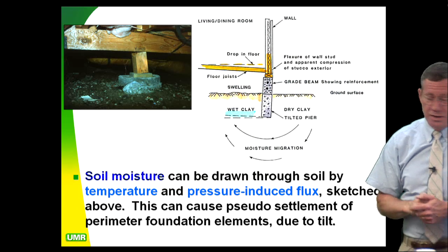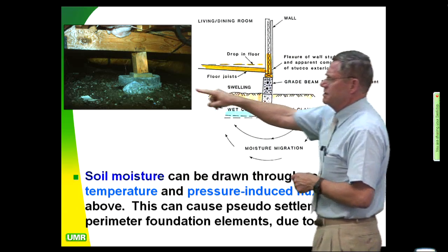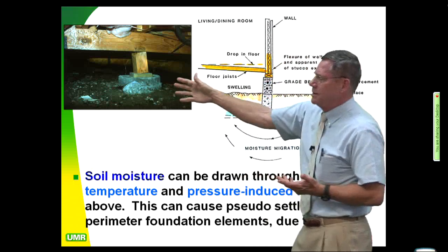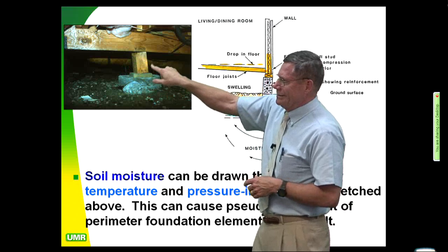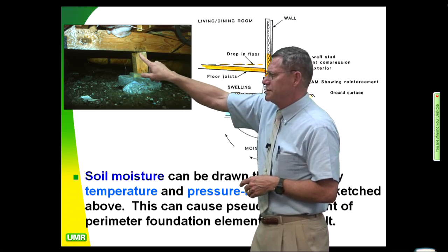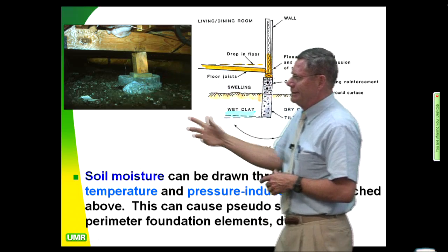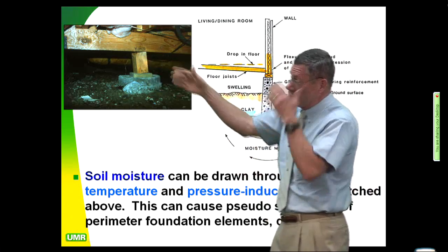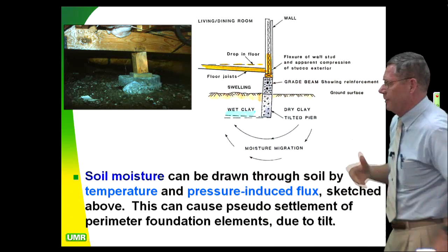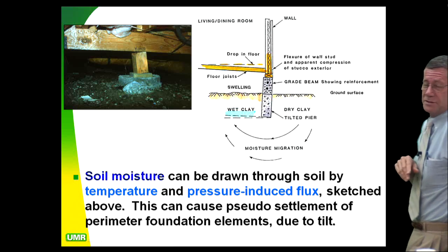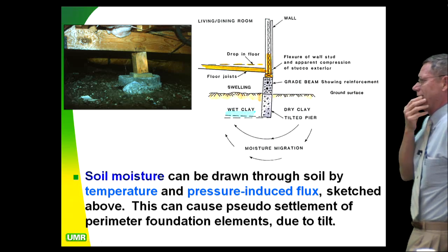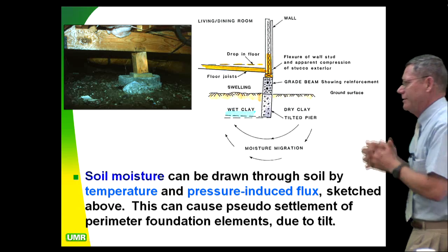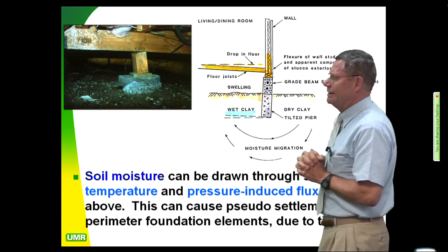Well, here's what happens when you crawl under a house and you look inside of it. This is in Silicon Valley, San Jose. Typical here, they have these 6-foot deep piers. They have a 4x4 treated wood post here, holding up a girder, and you can see the thing's rocking. And they're in earthquake country. So you're looking at that going, how old is this place? Well, it's 4.5 years old. How much did they charge for the house? $900,000. $900,000, and they couldn't even get to year 5 without having framing integrity checks? No, wasn't able to get there.